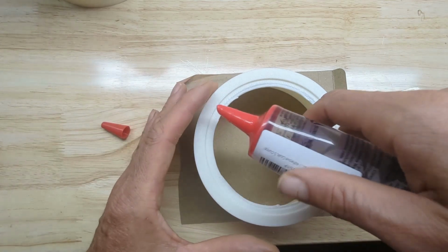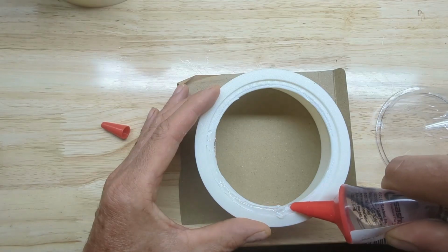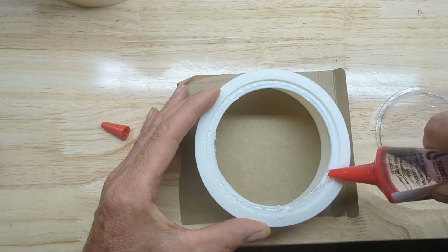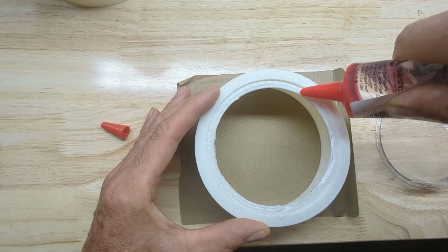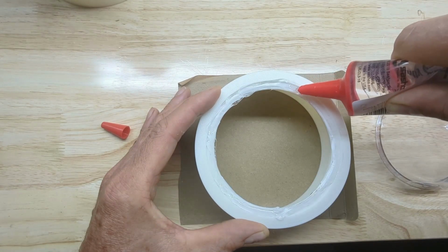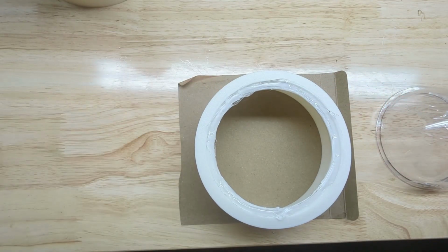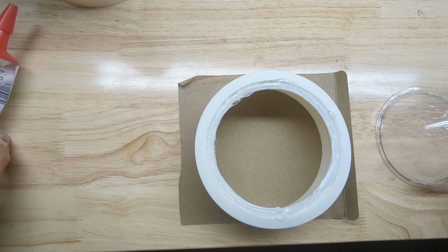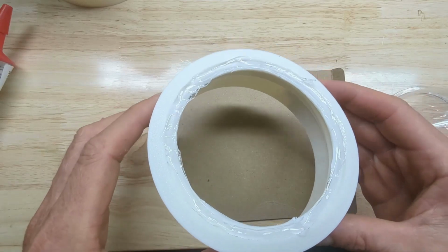So we'll go ahead and start applying this sealant, and make sure you cover all the way around. Don't let any gaps appear, because that could result in a leak in your dome, which is the last thing you want with your electronics inside. I'm not applying this as cleanly as I could, but it's going to be up in the air and nobody's going to see how ugly it looks. The main job is the functionality of the seal. So we can see all the way around, we got the sealant applied.